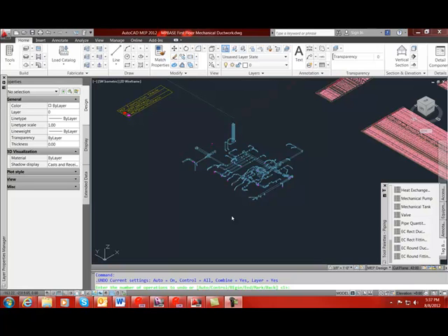Now that we have imported this selection, assigned systems, and corrected any errors that occurred in transforming the design drawing to fabrication, the next step is for us to apply the proper fabrication specifications to all of the ductwork, break up the ductwork, and remove any unwanted short pieces using Fabrication for AutoCAD MEP tools.